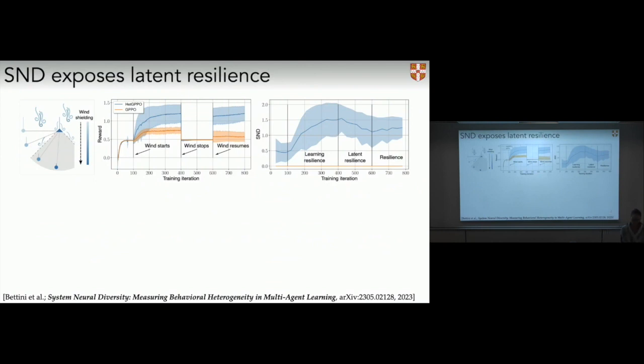We designed this task where we have two agents that undergo disruption during training. Here we have two robots, or two drones, that are flying in wind. They don't observe their shapes, but one of them is triangular shaped and deflects wind, and the other robot can lie in its shadow. The reward here is a joint reward, representing the amount of deflected wind as a group, right? So the more wind they deflect as a group, the higher the reward, the better they can fly as a group. And so what they have to learn here is, I'm the round robot, I'm the triangular robot, I'm the one that has to move under the round robot.